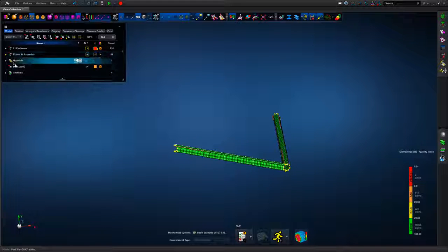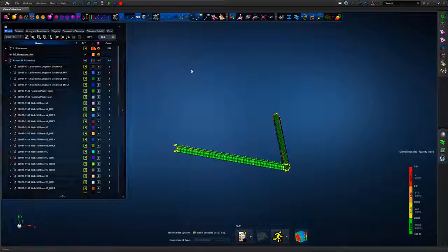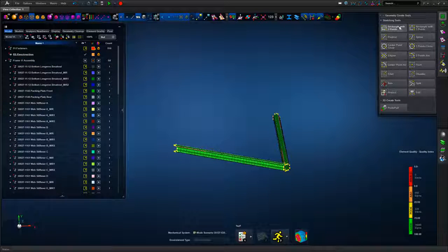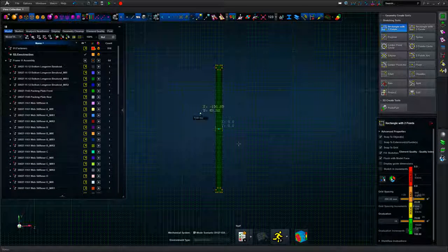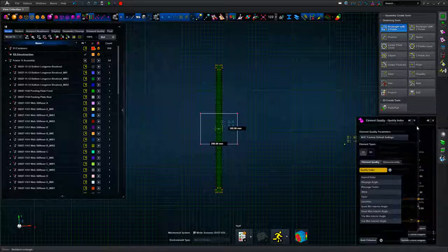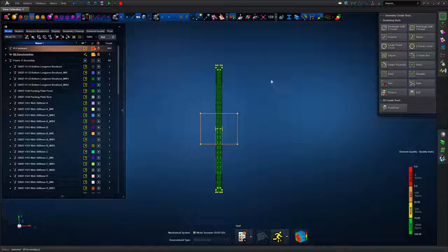So we're going to look at some of the sketcher tools. So we're going to create a new part construction, as it were. So any geometry that we use for creation or splitting or manipulation of geometry, and the resultant mesh is going to end up within that construction part. So we're going to sketch tools, and now we're just going to simply sketch on a plane, just a simple rectangle which we're going to use for cutting the components on screen.